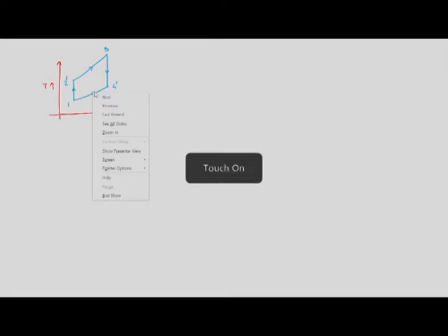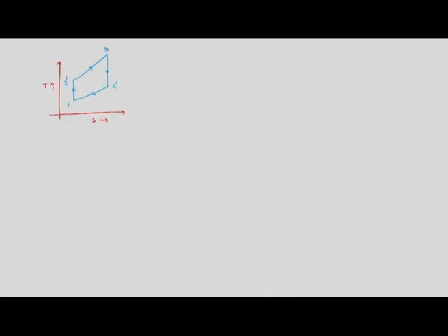So let us see a Brayton cycle with non-ideal components. Let us first consider the TS diagram, as we always do. We have the T axis and the S axis. Initially we will plot all the processes we already know, for the ideal cycle. So 1 to 2 is compression, but we will not say 2, we will say 2 dash for the compressor. Then 2 to 3 is the heat addition process. Then 3 to 4 is the expansion process in the turbine, but now we will say it as 4 dash. So we have 1, 2, 3, 4 as our cycle.